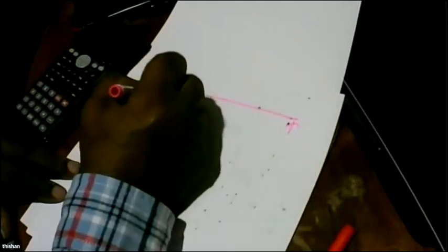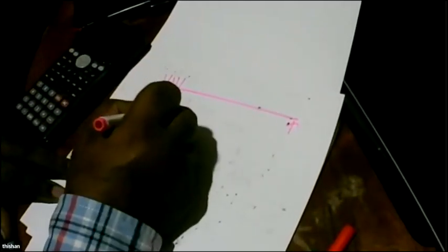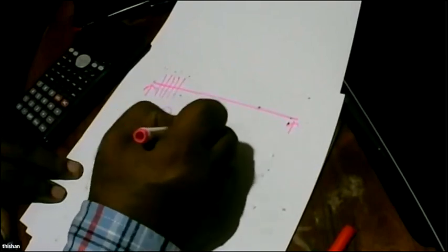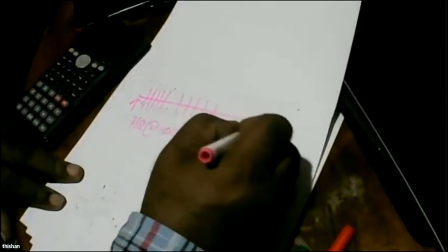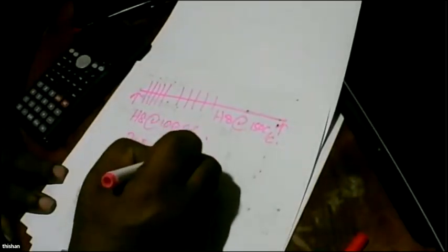So the chances are you will find that H8 at 100 center to center would be quite sufficient, and you can relax it to H8 at 150 center to center. Just do the calculation, because with my experience I'm telling you that when you have v as 1.14, this particular detail works.